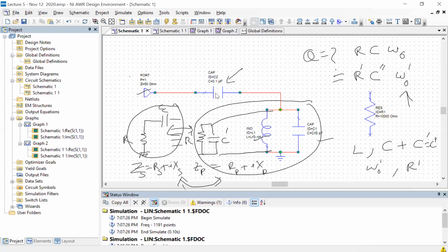So the frequency is more or less going to be the same value. So I'm going to equate these two impedances, Z series at omega 0 equal to Z parallel at omega 0. Only then will you see the expressions you're going to get.